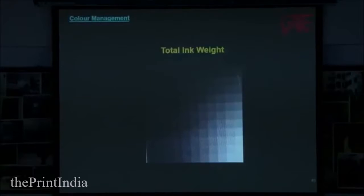So you get what we call a trapping problem. Trap is how the second color is sitting on top of the first color. So it's never 100%, it is always less than 100. So when you deposit this heavy ink one over the other, your shadow area will not get a good deposit of the second, third, fourth color, and then we have a trapping problem.